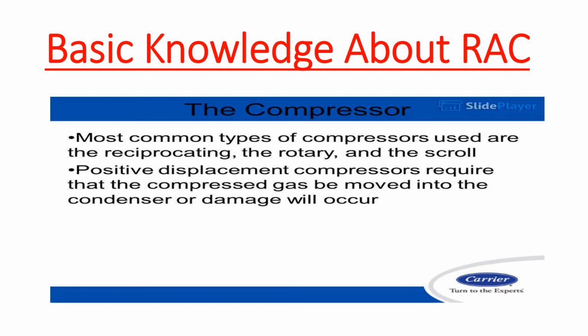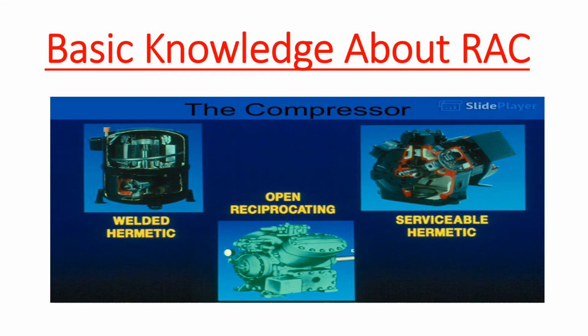The compressor. Most common types of compressors used are the reciprocating, the rotary, and the scroll. Positive displacement compressors require that the compressed gas be moved into the condenser or damage will occur.